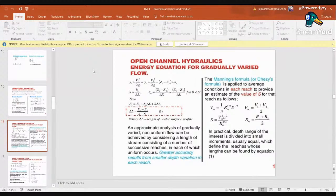Y is the depth of channel, or H is the depth of channel. A is the area. Capital P is the wetted perimeter, and capital T is the top width. Hydraulic radius is calculated as area divided by wetted perimeter, not area divided by perimeter but wetted perimeter. That is RH. And DH is nothing but area divided by top width, that is the hydraulic depth.